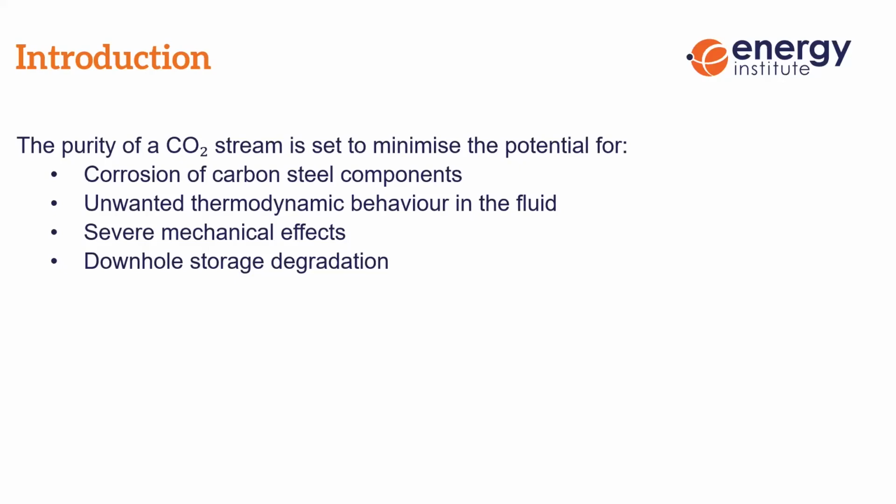And the reason for it is that the impacts of the impurities are significant because CO2 is not the same as natural gas, because it is an acid gas, where of course natural gas is not an acid gas. So we have to guard against the corrosion of carbon steel components.